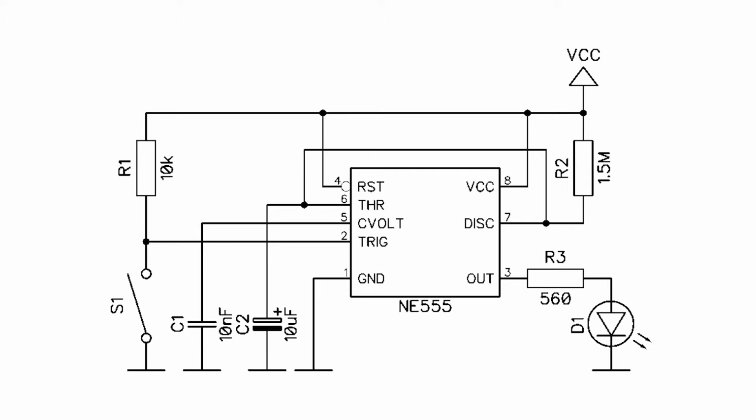At the moment of pressing the button, 0 volts is forced on pin number 2. At this moment, the flip-flop switches off the transistor and displays the high state on out. The capacitor is charged until the voltage is equal to the one necessary to reset the output, thus 2/3 of the VCC voltage. The cycle will be repeated only when this event occurs again at the trigger input.